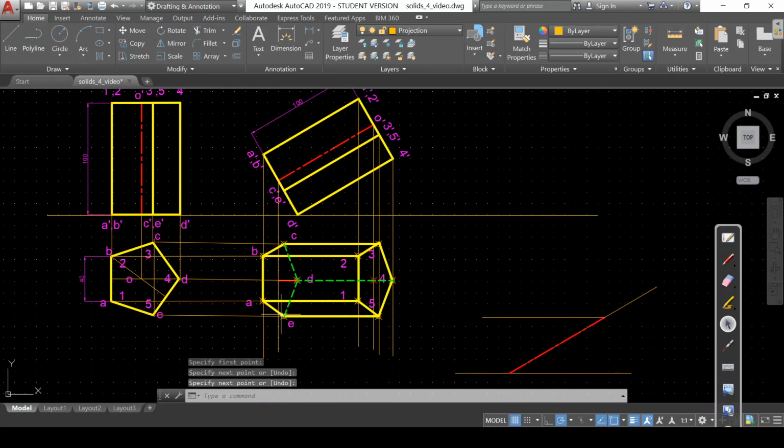Okay, so top view, the apparent length of the axis is there, this angle is different. Okay, this is making apparent angle, but they want that the true length of the axis making true angle with VP. So true length we have marked at 30 degrees, that is the true angle. Now for drawing this top view, we will find out the apparent angle. For that purpose, let us select this length.